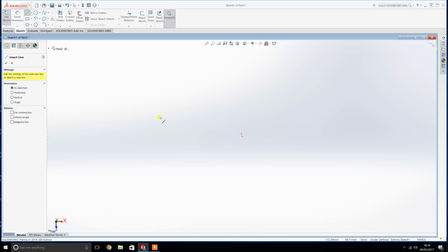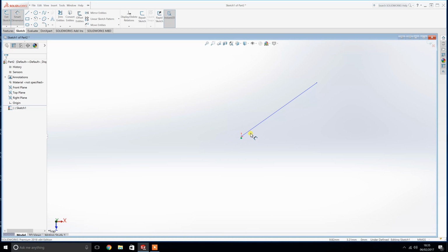To begin, I will just draw a simple line by clicking in the center and dragging out. This line is an undetermined length. As you could see, when I clicked on the endpoint, the sketch tool gave me the option to continue sketching. Just press Escape to cancel and go back to the default options.